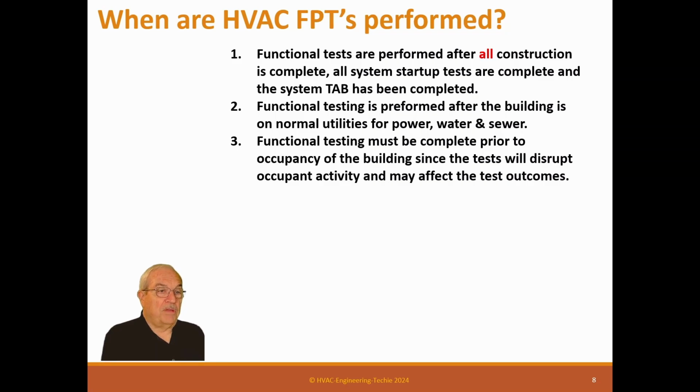So here's what normally happens, and we've mentioned this in the previous video: the general contractor has missed schedule days or things that didn't get done on time, and so it begins to get longer and longer, but the actual start date, the turnover date, doesn't change. So he's actually compacting the end of the schedule, which is your testing time. That's why I keep telling you that functional testing is a critical path. You cannot allow a functional test to be truncated.